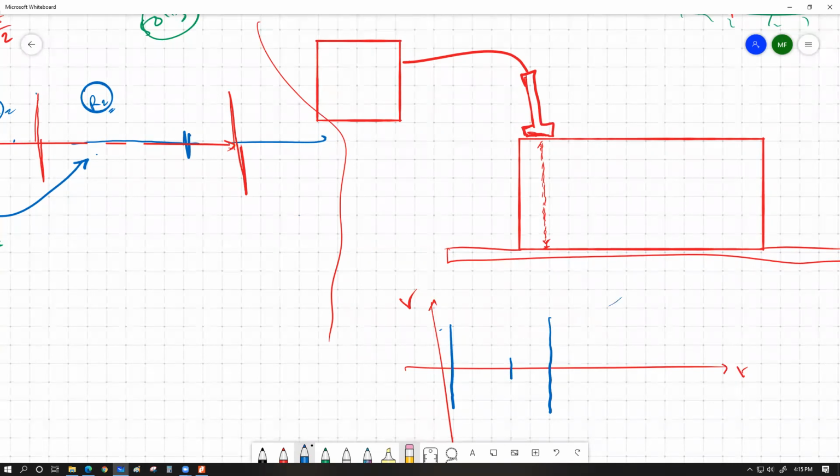Let's say all the send pulses are sent 5 divisions apart on the whiteboard dots, and the reflection is received at 3 divisions. As long as this piece of iron has a uniform thickness all over, it doesn't have any problem. The sound is reflecting off the bottom surface of the iron and eventually coming up.